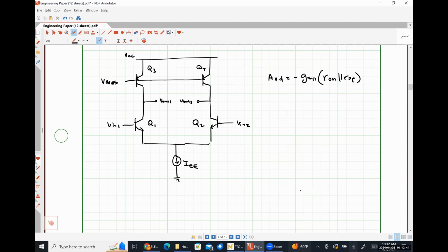One way to do that would be literally to just ground one of the outputs so that we only care what's going on with V out 1. Why would that be problematic? We're going to get exactly half of the gain of the circuit because the other output is always tied to 0. There's a way around this where we load this guy with a current mirror.